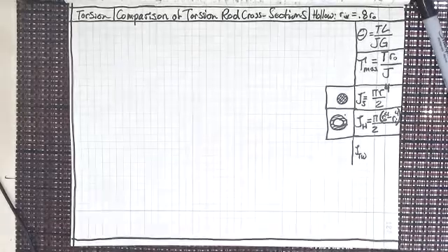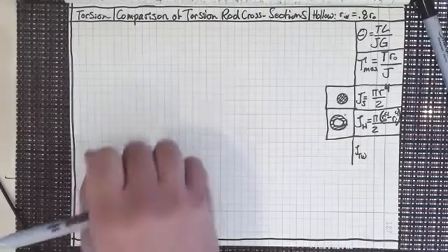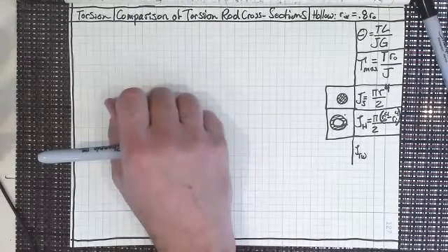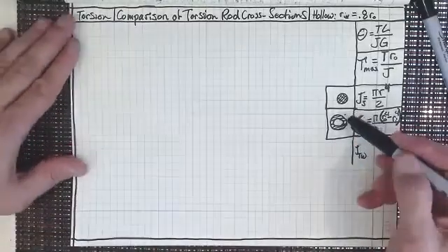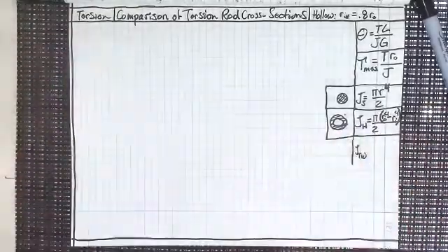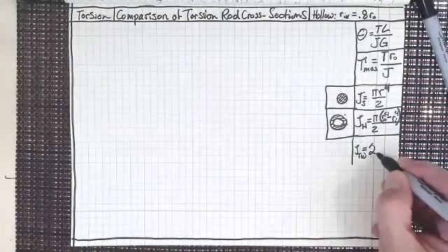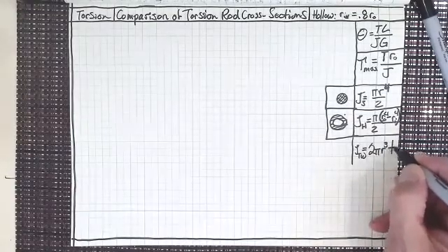That happens to be a hollow cylinder, and the reason that we make it a hollow cylinder is more for the flexure. If I made it just a solid cylinder, the thing would flex too much and be, you know, breaking itself. So we've made it with a hollow cylinder. Could we make it with a thin-walled cylinder? You know, there would be other problems that we would run into with a thin-walled cylinder. So we want it to work in a flexure mode too. So that's that. Then the thin-walled moment of inertia is 2 times pi r cubed times t.